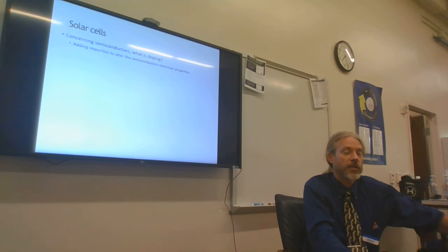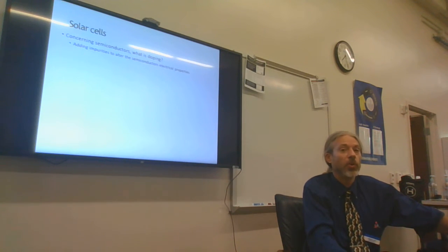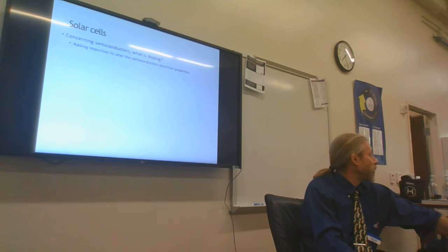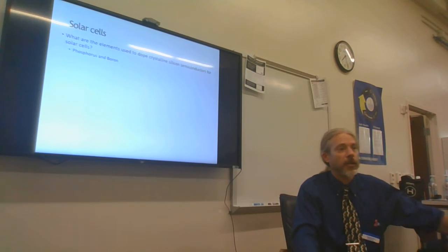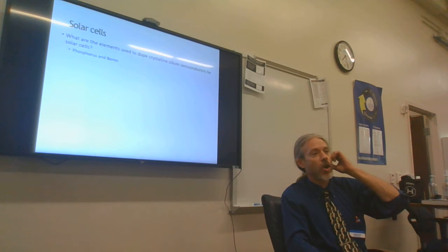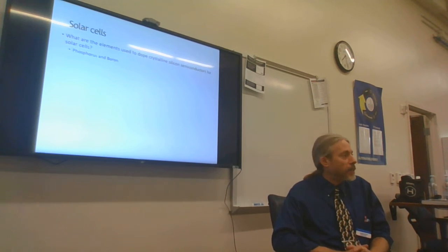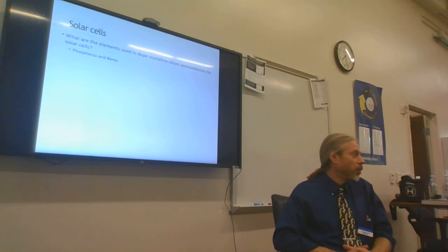99.9999% pure silicon. Even one part out of a million parts will dramatically affect the semiconductor qualities. The main purpose is to create N-type and P-type silicon. N-type being doped with phosphorus, P-type being doped with boron. Phosphorus has an additional element.